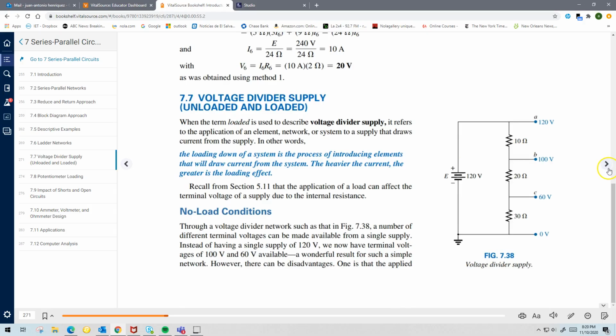All right. This section, I'm only going to mention one thing, and this is what I mentioned also in the lab. Things are different when you have a circuit with what is called no load, and when you have a load on it. For example, remember what I always said in the lab: if you're looking to have a voltage in the circuit, in the protoboard, don't always trust what you see in the power supply display.